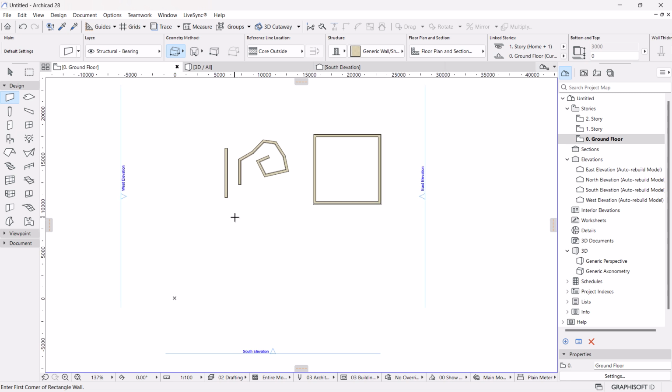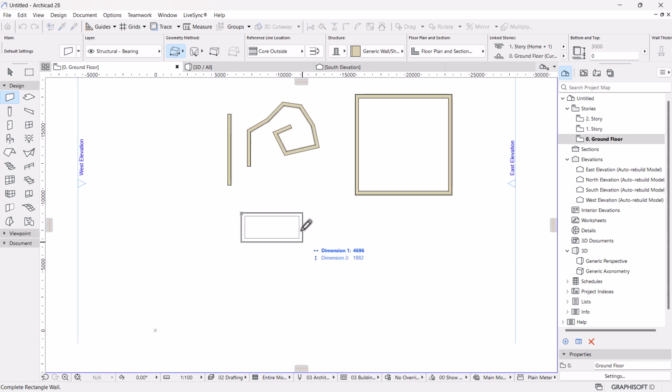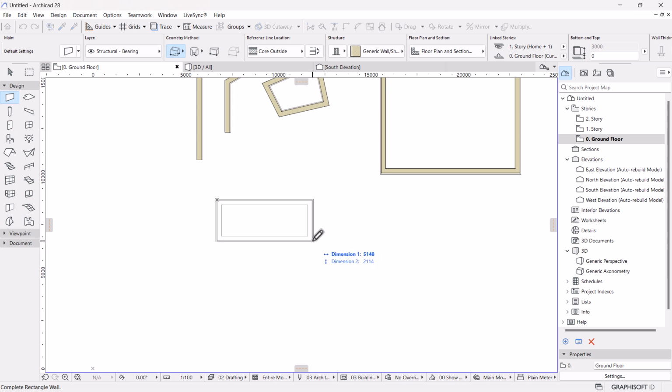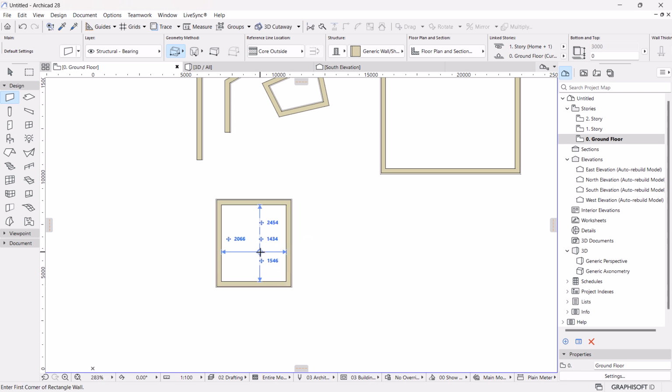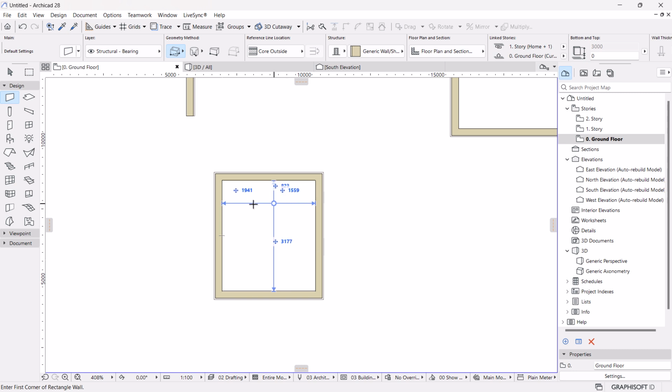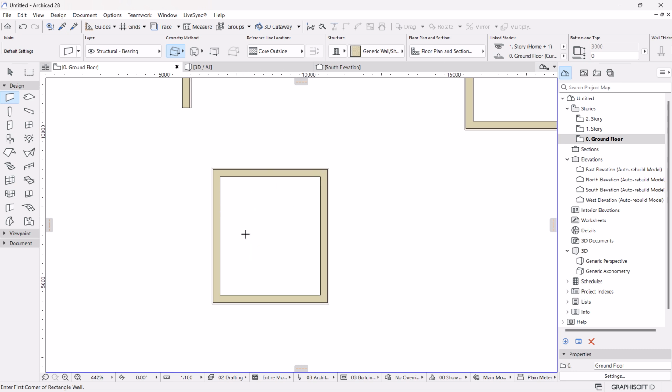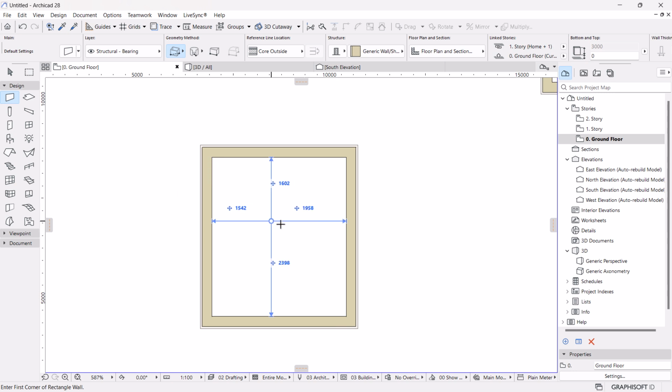As you're doing this operation, you would see we have this tracker, the dimension tracker, where you can key in the dimensions of what you want to achieve. In this case, you could say 4,000 millimeters, and to access the vertical dimension, you have to click on the downward arrow on your keyboard, then key in the value again. With the latest version of ArchiCAD, you would get the distance guide, which is a very critical game changer in terms of how your spaces look.